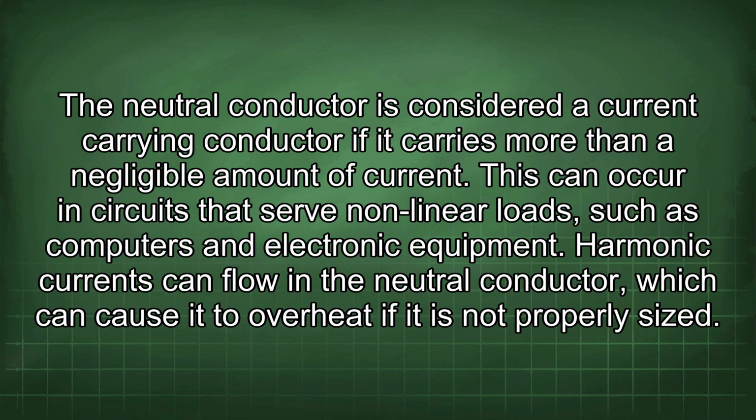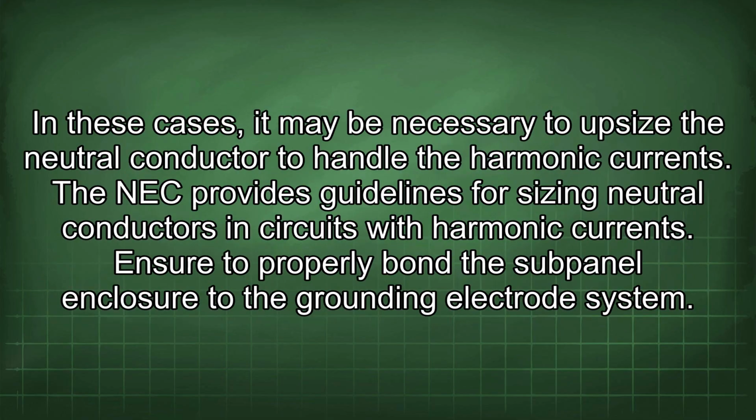The neutral conductor is considered a current-carrying conductor if it carries more than a negligible amount of current. This can occur in circuits that serve nonlinear loads such as computers and electronic equipment. Harmonic currents can flow in the neutral conductor, which can cause it to overheat if it is not properly sized. In these cases, it may be necessary to upsize the neutral conductor to handle the harmonic current. The NEC provides guidelines for sizing neutral conductors in circuits with harmonic currents.